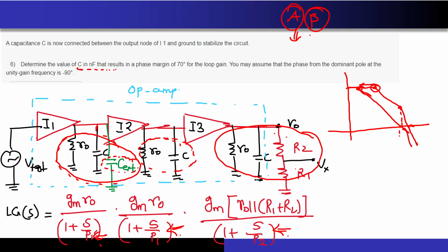Because this feedback R2 by R1 is connected across a point which is seeing a finite output impedance. So you have to take that loading factor into account, and to do that you have to go back to the feedback theory, and in that way you can separate out these two, the feedback network and this. Remember, this is not an infinite output impedance now, this is a finite one. So while you are removing R2 by R1 from here, this is, let's say, your open loop network now. So you have to put some load over here to make sure that the location of the pole will not change. That is what we call the loading effect, and this has to be taken into account. This ZL has to be calculated separately and it will become a separate headache.